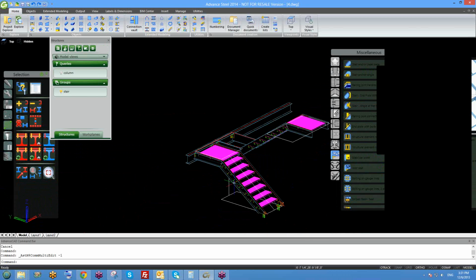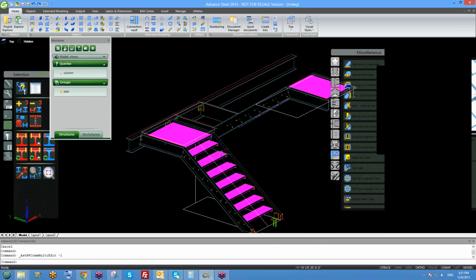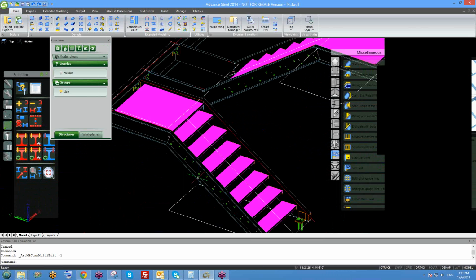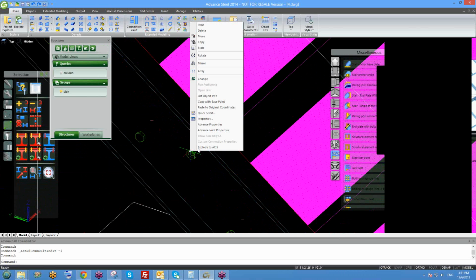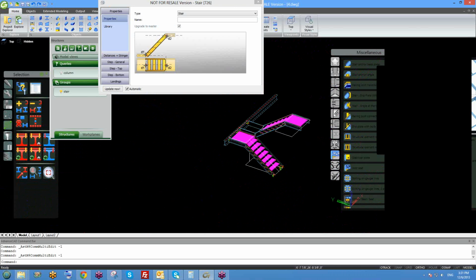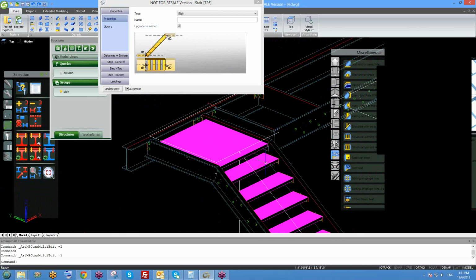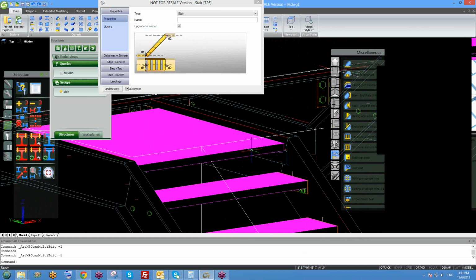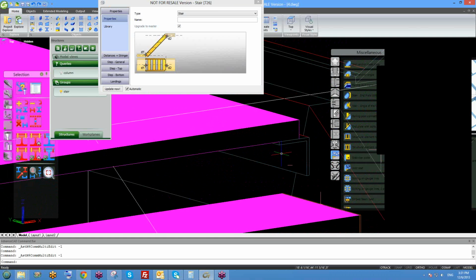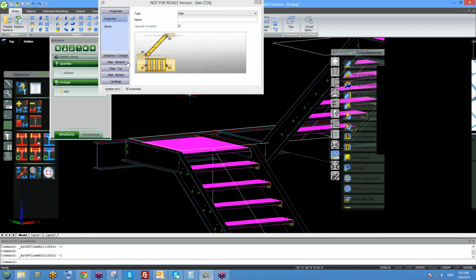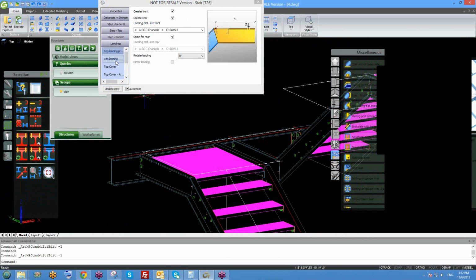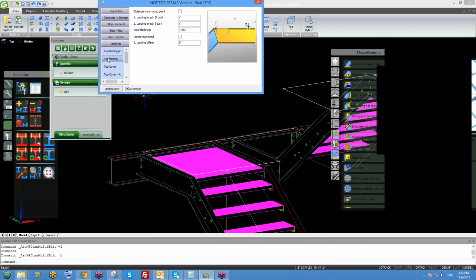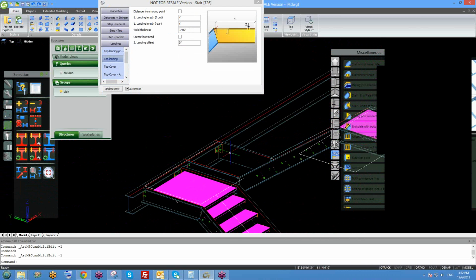The stair is like any other connection in Advanced Steel. You can select any part, this little bolt, and go to Advanced Joint Properties. So now, if you want to add this grating and this angle, you need to come in here under landing because it's your landing. In this case, top landing. For this one, it's going to be your bottom landing.